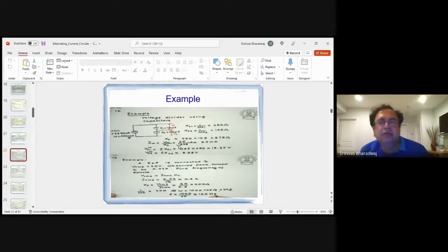Therefore your xc goes up because it's additive, right? But the net capacitance goes down. Okay, so you just do an add of these two, therefore you end up with 375 ohms. So 25 divided by 375 will give you the Im.